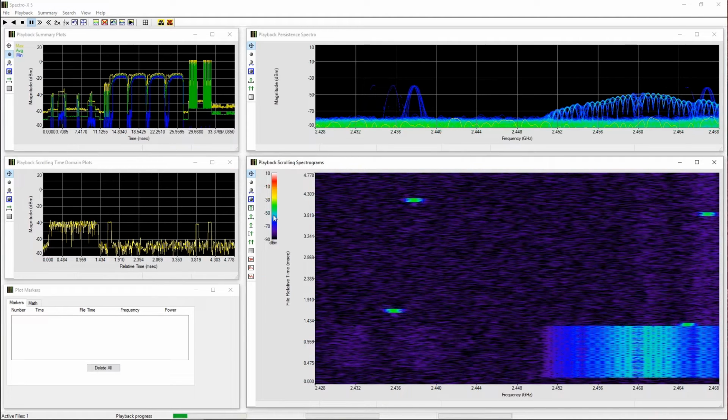The best and easiest way to go about doing that, or what I'll do here now, is say I'm interested in specifically this little portion of signal here. This is a Bluetooth hopper for any of those that are interested. Say I wanted to pull out just this specific bit of information and send that into my secondary analysis tool.